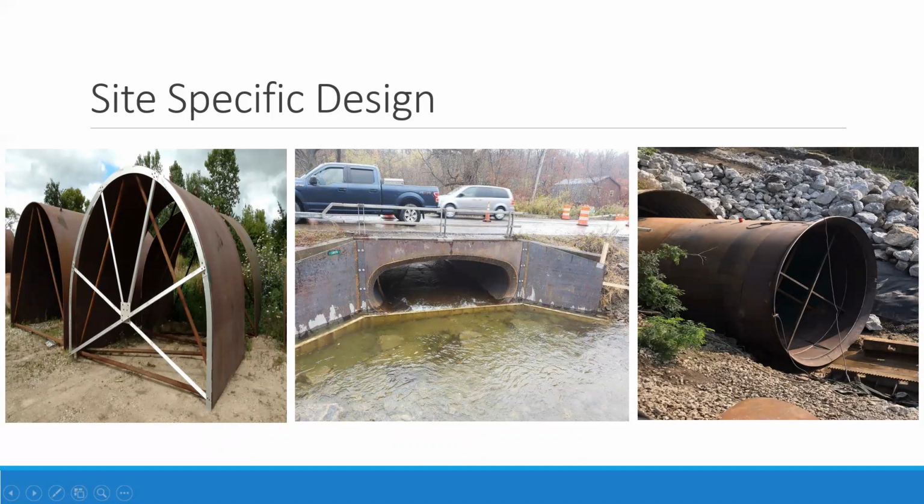And in order to accommodate an effective slip line, the InfraSteel liner is downsized approximately 6 inches from the existing structure's dimensions. So you've got roughly 3 inches of annular space between the existing structure and the InfraSteel liner. That would be filled with flowable fill or cellular grout once the liner is installed.